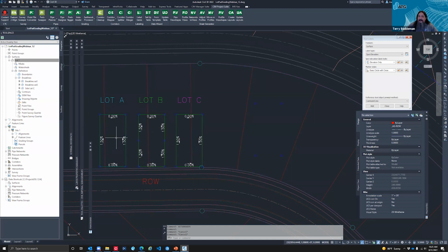We have 3 different templates: sloping forward, sloping back, and then one that's kind of crowned in the middle, sloping. The high point would be in the middle here. And basically all these are just feature lines. We can develop different feature lines for our objects here, and it's just a pretty simple approach, just grading a feature line by object, and we can apply that to our grading family.